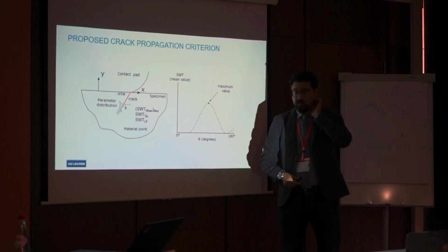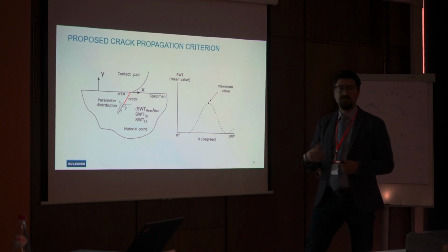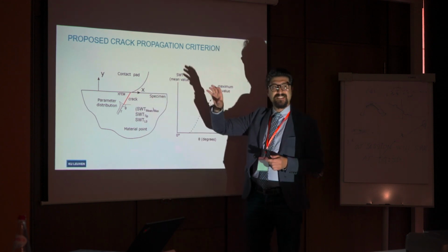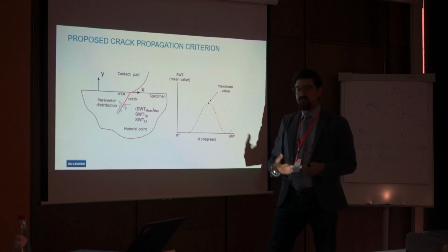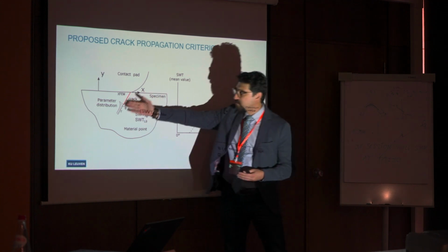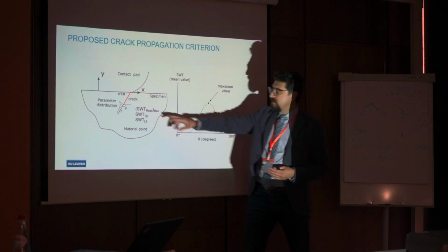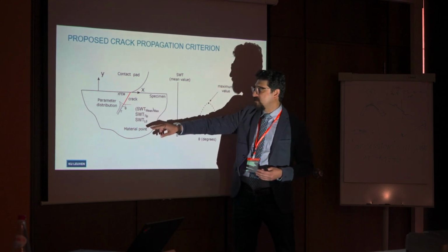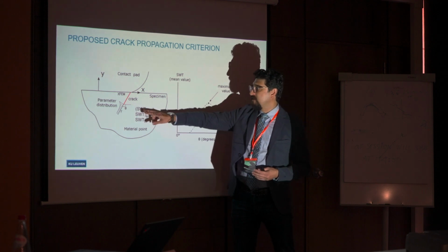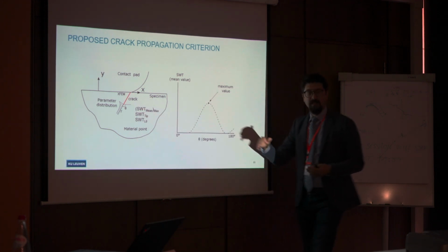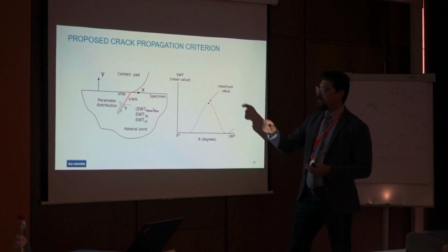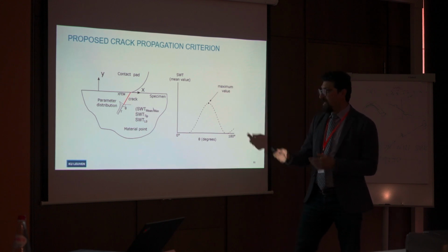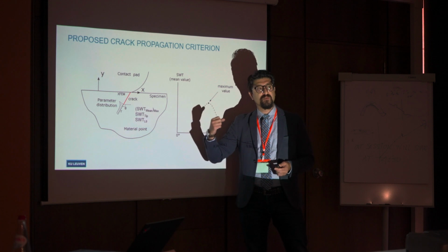Next, what we had to do was combining this wear effect with the crack propagation. But as I said, the stresses here are very non-proportional. So we use XFEM in a single mesh, but we also try to come up with a new idea for how to predict the right crack path using a new technique. So we used, again, the stability parameter, but in 3 different ways. One, extracting that at the crack tip, one at the critical distance, and then again, one, the maximum value of the mean stress, actually the stability parameter, around the crack tip to find the next kinking angle of the crack. So in that way, we were hoping to be able to capture this non-proportional stressing.